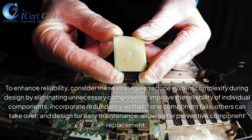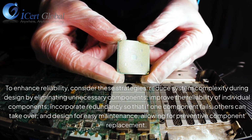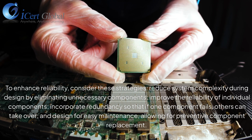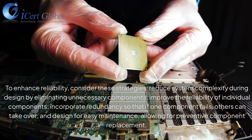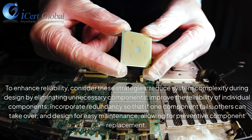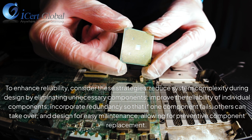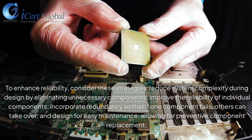To enhance reliability, consider these strategies. Reduce system complexity during design by eliminating unnecessary components. Improve the reliability of individual components. Incorporate redundancy so that if one component fails, others can take over, and design for easy maintenance, allowing for preventive component replacement.